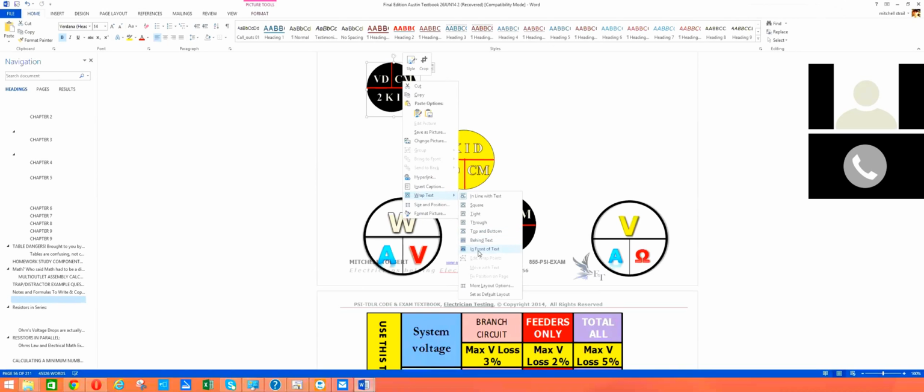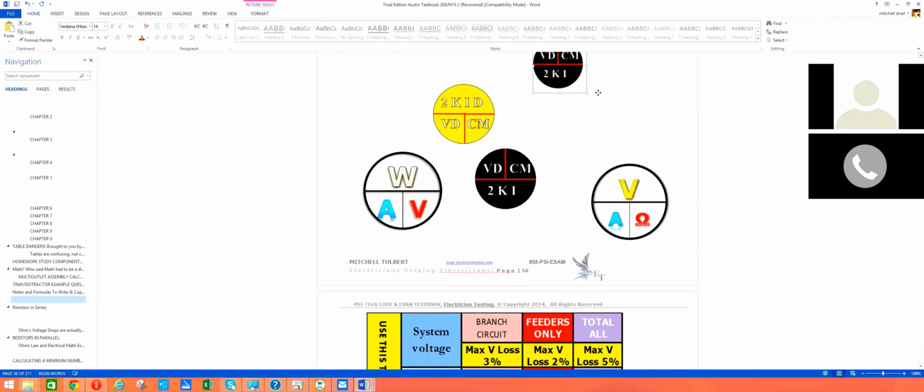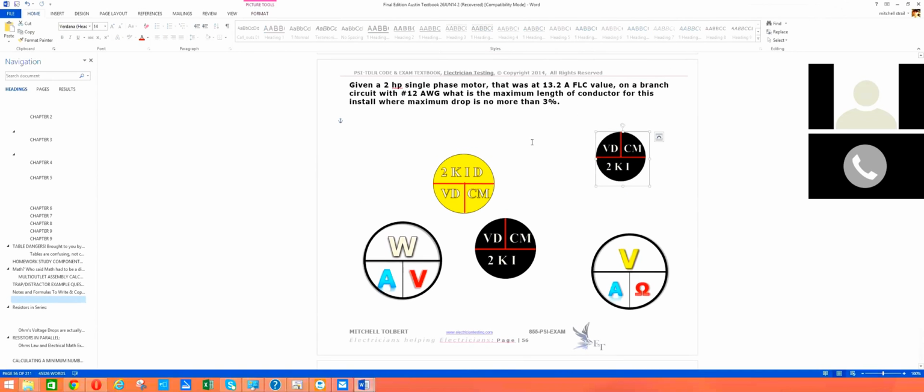Yeah, I tell you, the thing about the 746 is it's got really absolutely nothing to do with these calculations. When you're sizing conductors and trying to size a demand load for branch circuits, for motors especially, specifically in 430, they give you a requirement to use the table values listed under 430.248 and 250 on pages 350 and 351 of your code book, to use those demand values that are calculated with the FLCs listed there. So if you look on page 350,